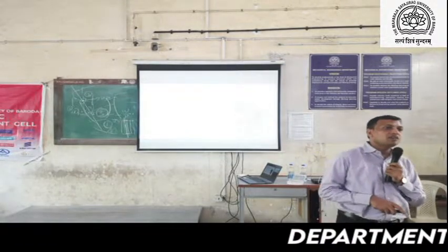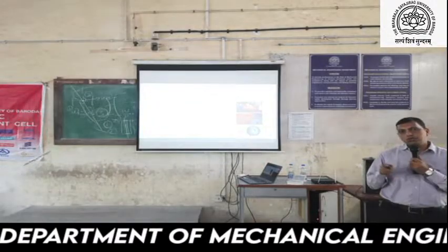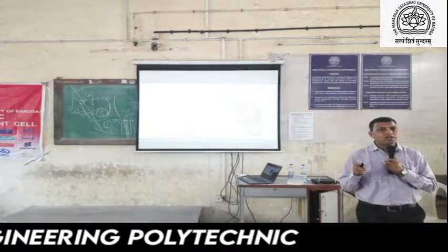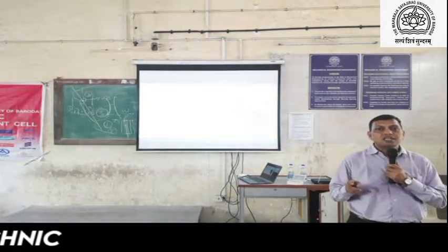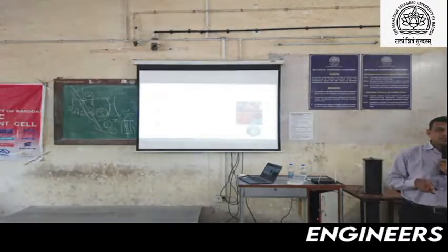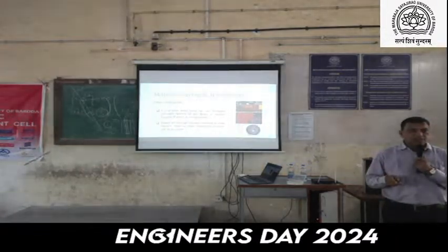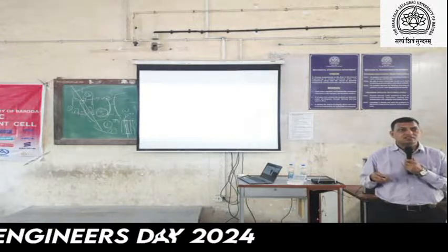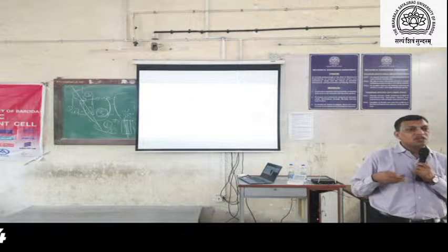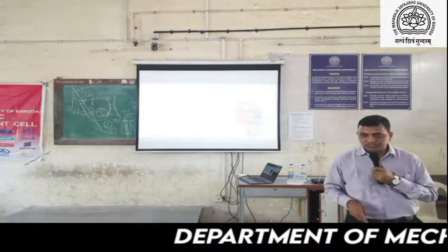In case hardening, we just harden the tooth area. That means the tooth area which comes in contact should be hardened with a particular depth. That is related to the module as well as the application, how much case depth we require. For that reason the heat treatment cycle should be considered. So if we require a particular depth in X, the related time should be considered in Y. So if the X value is increasing, the Y value is increasing in parallel in the heat treatment process.